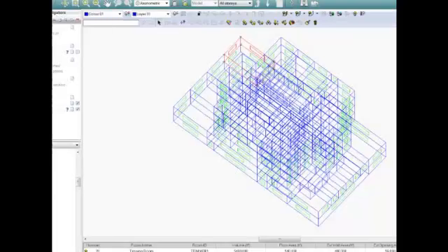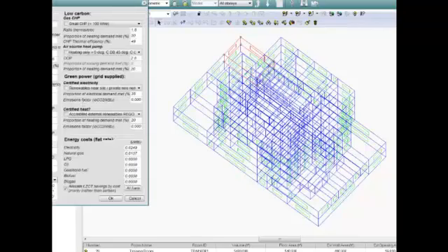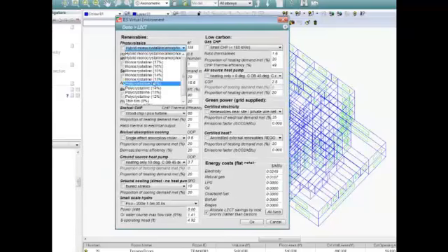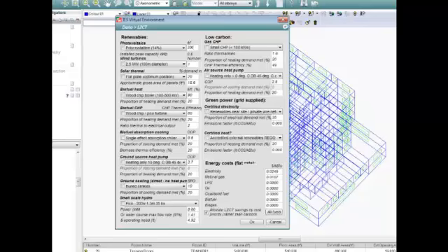When we go into a later type of analysis, I'm just going to check down to my low and zero carbon technologies and open this up. I can then run the same analysis, but then start to specify with more detail. So I'll say that I know we can afford 2,000 square feet of polycrystalline solar panels versus 2 of these type of wind turbines of 5-meter diameter.